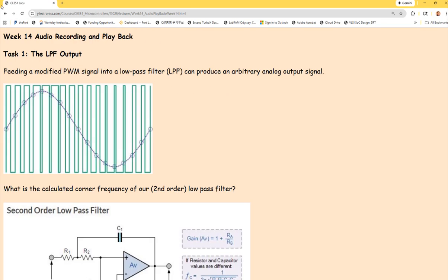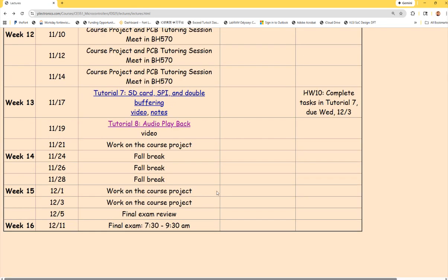So the concept here is that we want to record audio signal to the SD card. If you think about that, you are using an ADC to sample data. It's probably for one of the senior SAM teams, maybe Luke's team. So they are doing some testing and ADC sampling, data acquisition. So the data acquisition is at a pretty high speed. So in that case, you need to sample it and store it onto the SD card. And just in case, right after it, you want to play it back.